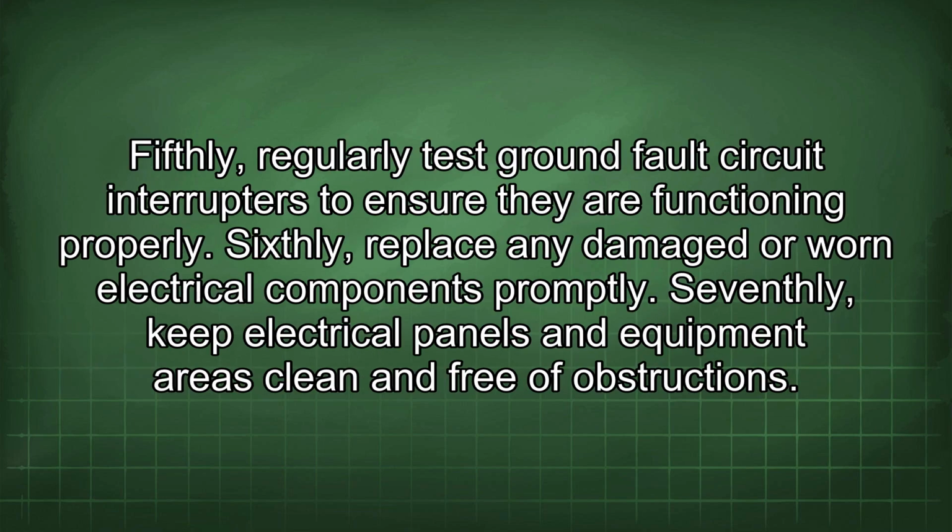Fifthly, regularly test ground fault circuit interrupters to ensure they are functioning properly. Sixthly, replace any damaged or worn electrical components promptly. Seventhly, keep electrical panels and equipment areas clean and free of obstructions.